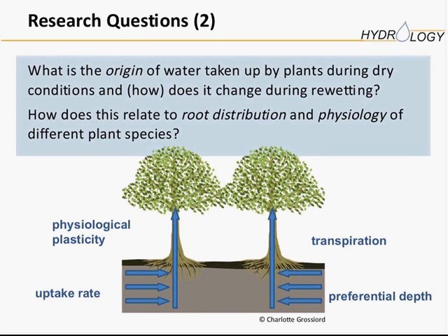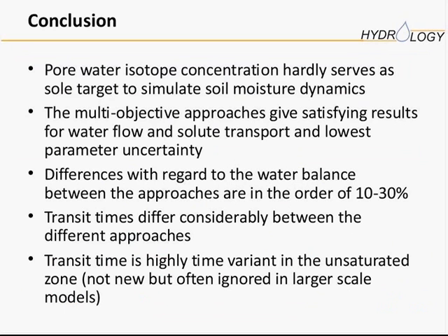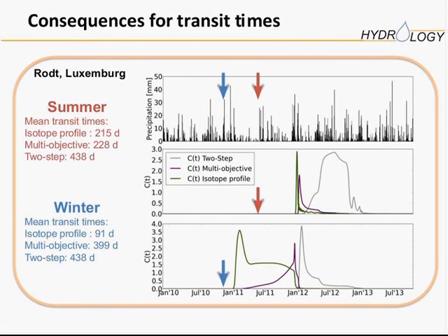No, in this case, really, the shape is given by it's still okay. In this respect, you have to believe that Richards' equation works for this kind of soils, right? And we can certainly debate about that, if preferential flow may be important for some of those processes. But from the simulations that we did and the forward modeling, the shapes of the distribution that we get, just an example here, are really a consequence of the soil properties, the water movement, and the evapotranspiration or the root water uptake. Right?